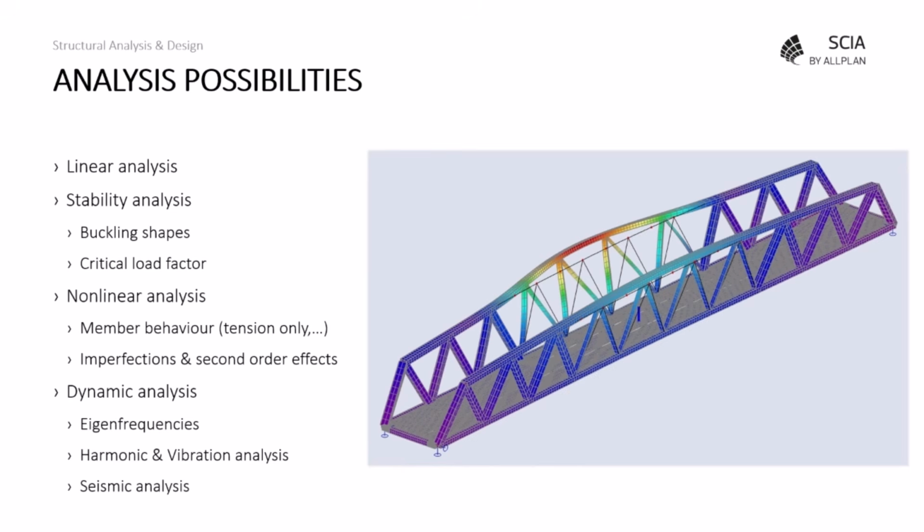Also, dynamic effects can be taken into account in the analysis. It's, for instance, possible to calculate the eigenfrequencies of the structure. For bridges, this is relevant to evaluate if vibration effects should be considered or not. For regions where seismic activities can occur, a seismic analysis can be performed.